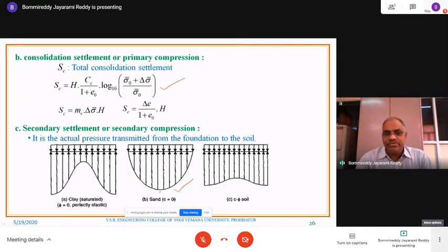Always it is difficult to reproduce the same diagram unless you know some imaginary methods. So while walking on the sand, you will get more pain at the center part of your foot. That is possible only when there is a high intensity of stress at the center, and at the outer area there is no stress. Almost stress will be equal to zero. This is the variation of the stress diagram on sandy soils.